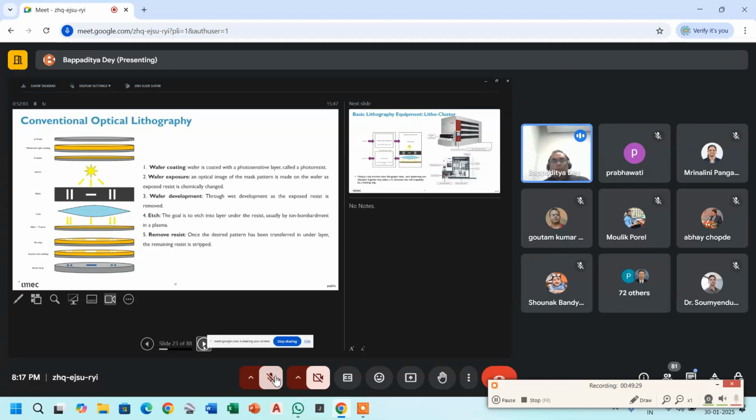You generally expose that design in the tool using some light source. You do some chemical and some physical activities there, physical activities not by you, but from the tool aspect. You have a lens, and this is driven by physics laws, the optics. I'm not going through the details, like interference, diffraction, all these things. The lens is going to gather the diffracted light of several orders.